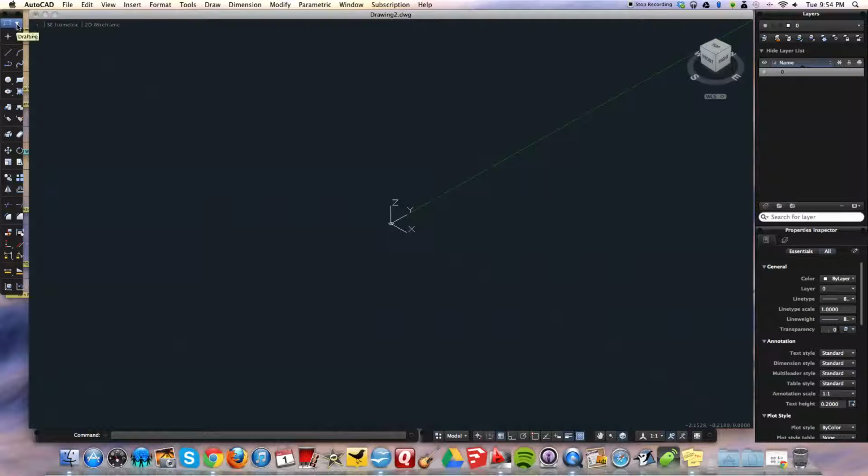And I haven't shown you the 3D toolbar. So right now we've been using the drafting toolbar up here, and we've used annotation to do dimensions. But we're going to use the modeling toolbar, which is mostly what you would do for 3D functions. So, modeling toolbar, second row in, there's one called box. I'm going to show you what box does, and I'll show you a couple of these other ones. I'm going to click on box.